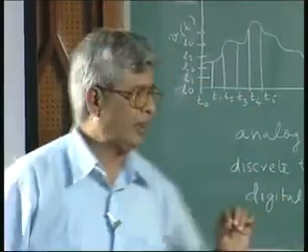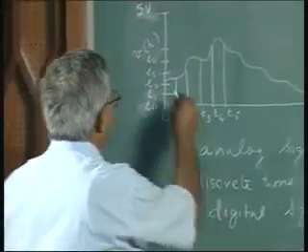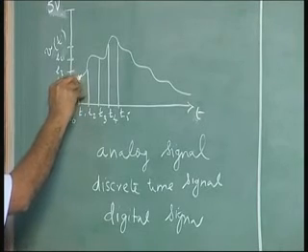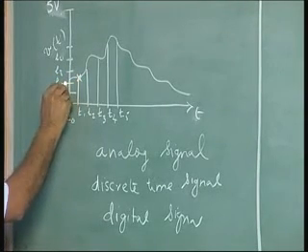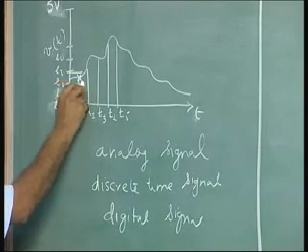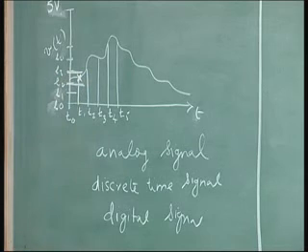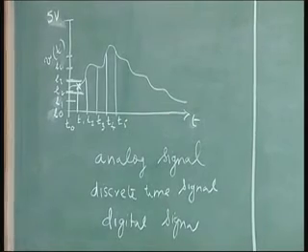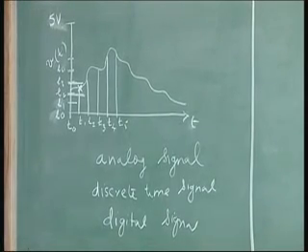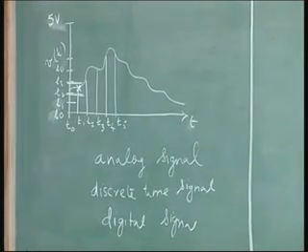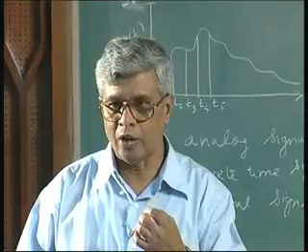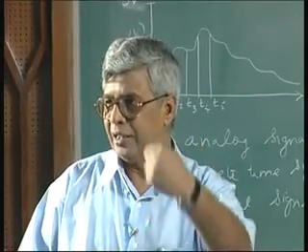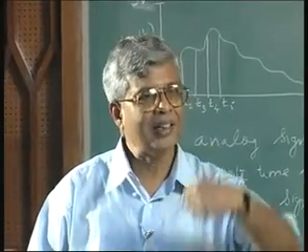Now suppose I want to represent the signal value at T1. It is between L2 and L3. I cannot say it is between L2 and L3. It is not possible to store or transmit between L2 and L3. I will have to either transmit L2 or L3. I have to make a prior understanding. I will always round it off to the nearest lower level or nearest upper level.